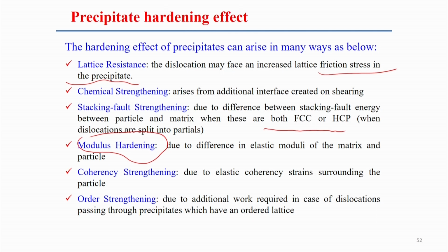The formation of precipitates or carbide particles imparts hardness, but at the same time there is a loss of hardness because carbon atoms exit the solid solution and form the carbides.